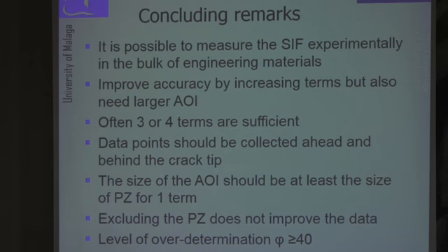To conclude, the first thing is that it is possible to measure the stress intensity factor experimentally in the bulk of engineering materials. Some people have done something along these lines, but here we've done a thorough analysis of what the parameters are and how well we can estimate the stress intensity factor.